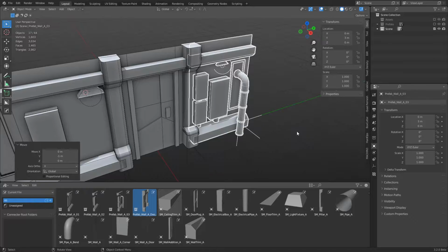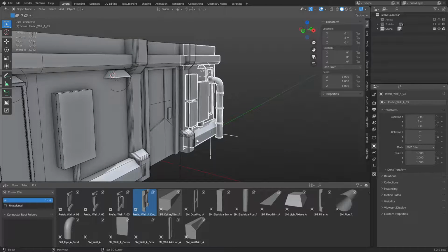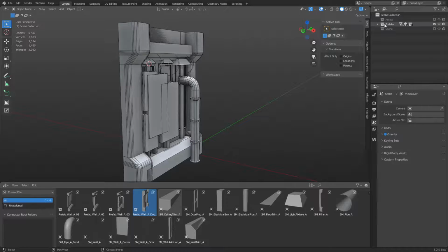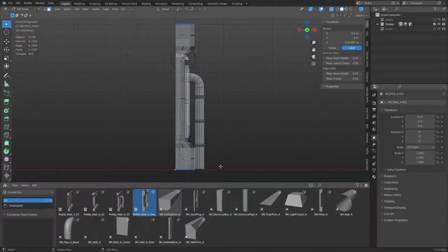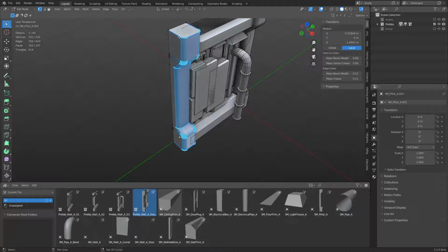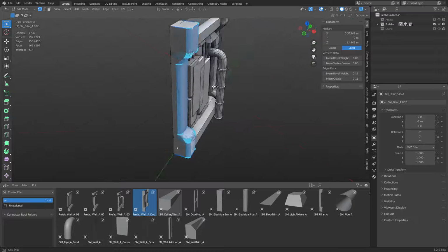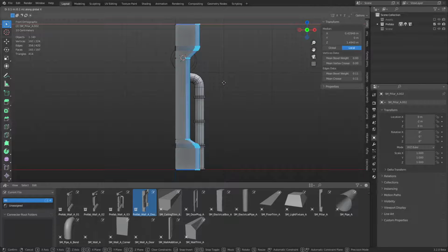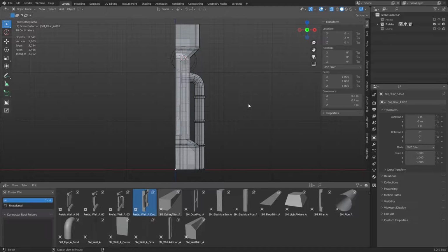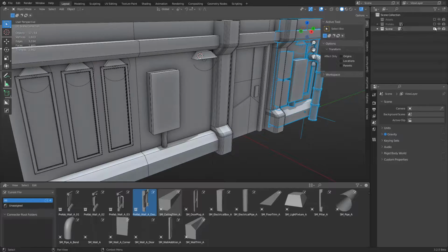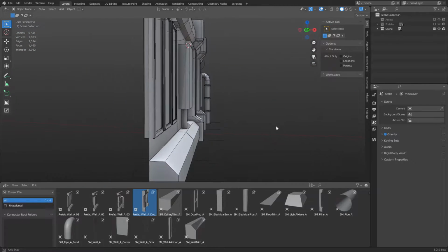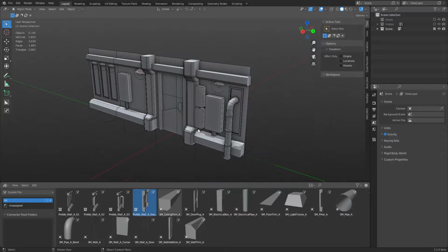In this case, this pillar is not working for me. Go back to prefabs, select one of them. I'm going to bump the whole thing out, I think. So we're going to bump this out to the grid, active element, okay. So we'll go just 10 centimeters more. That should correct that little issue. Turn them back off, come back here. Now we don't have Z fighting. Nice. Okay.